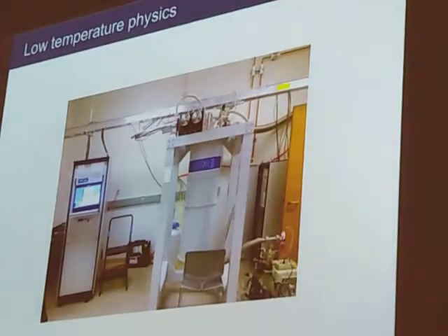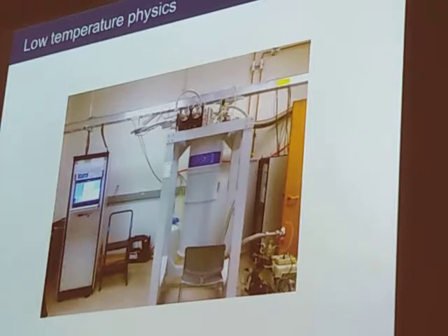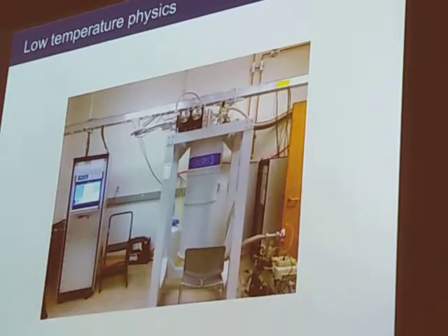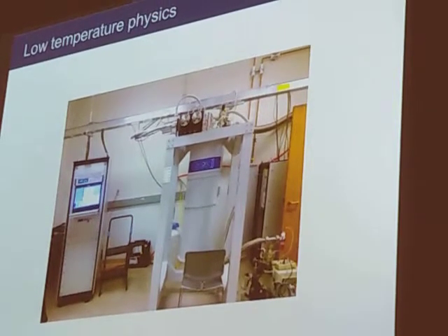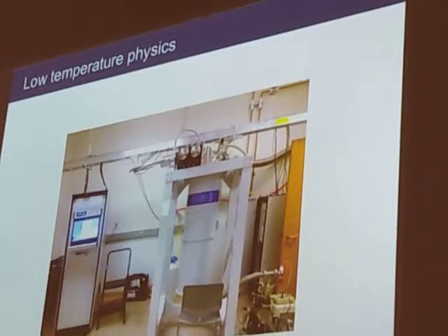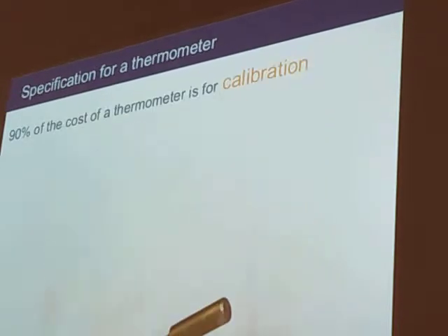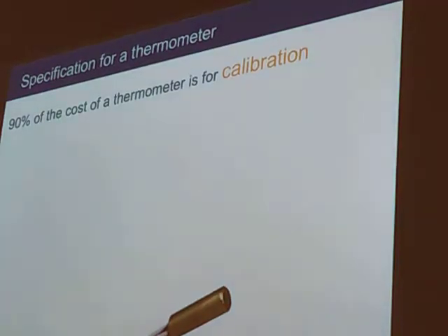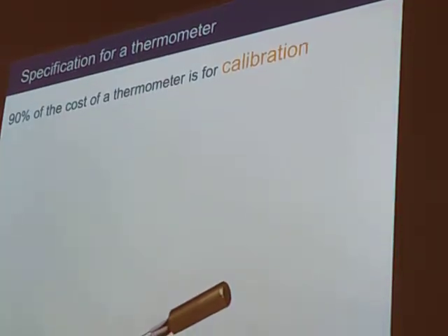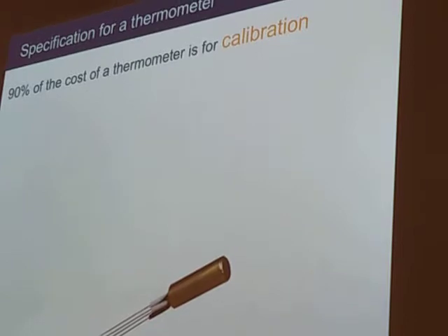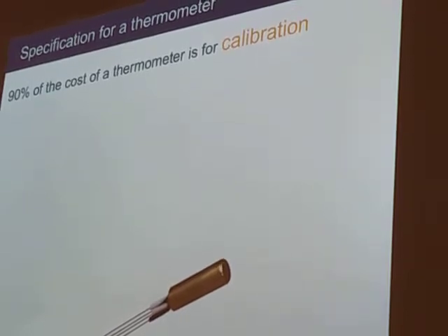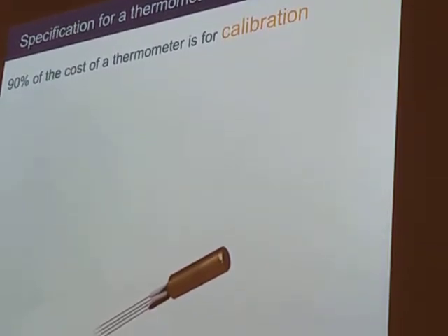And another one that we've been doing is almost at the other end of the temperature spectrum. It's a project we've been doing entirely in-house in the physics lab in Cambridge, and that is to design a material for use as a cryogenic temperature thermometer. So there's one of these fridges, and this is what one of these thermometers looks like. With this thermometer, you measure the temperature by measuring the electrical resistance of the material, and then you have a graph to convert that into temperature.